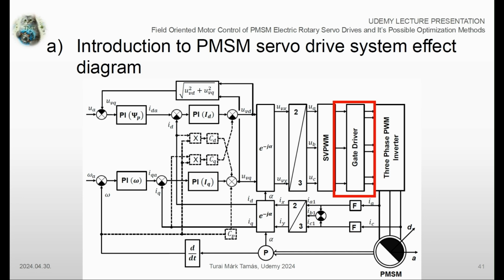However, in this course, we are going to use software-in-the-loop, so SIL simulations, for the validation of our FOC software. Hence, the gate driver is not going to be a real part in our simulations. Finally, I'm going to give you a previously built plant model that we are going to configure together, containing the three-phase voltage inverter and PMSM motor as well. This is simply needed because the implementation of the plant model could be an individual course content altogether.